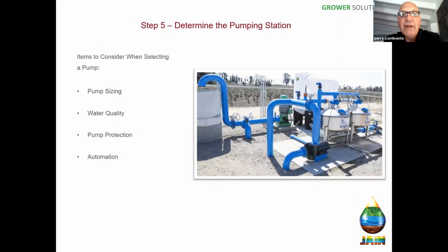So now we're going to go to the pumping station, and here we're going to appropriately size our filters. We're going to appropriately choose our filters. What kind of filters do we want? So we're going to probably confine our discussion to sand media filters because they tend to be very popular here in California on the West Coast. But there are other choices that certainly can be made.